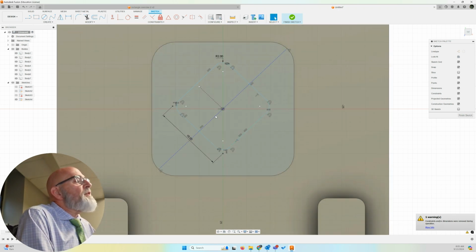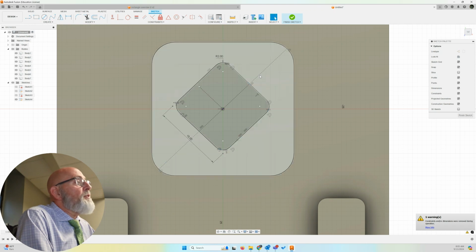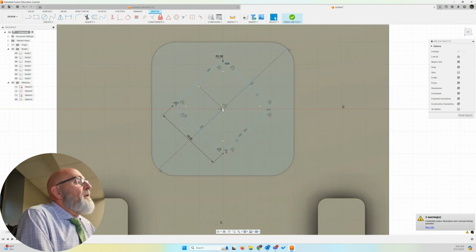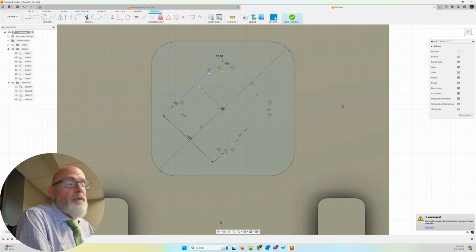So if this is the center line, going from the center of this diagonal, center to center, means that's the center line. We want this to be our center. That means this line must be 7.5 millimeters from that line, right? And that this line, because that's 45, it's perpendicular to that line off the origin, which is the center of this.